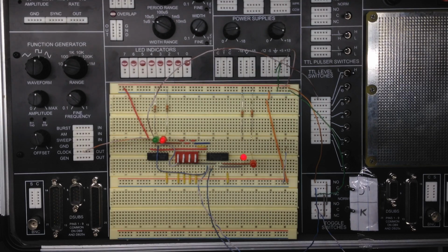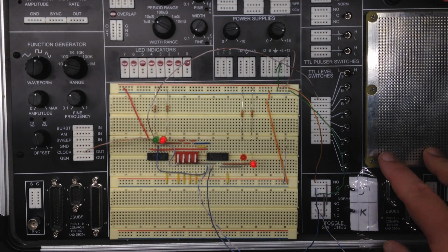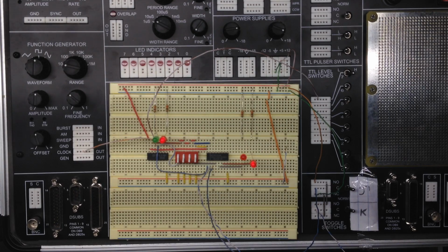We're going to change over to the 112, take a look at the function table for it, and walk through the different pieces that we have there. We have two inputs going into the 112, whereas with the D flip-flop we only had the one. We have inputs J and inputs K that we're going to be dealing with here. We also have similar function with the preset and the clear and the clock coming in.